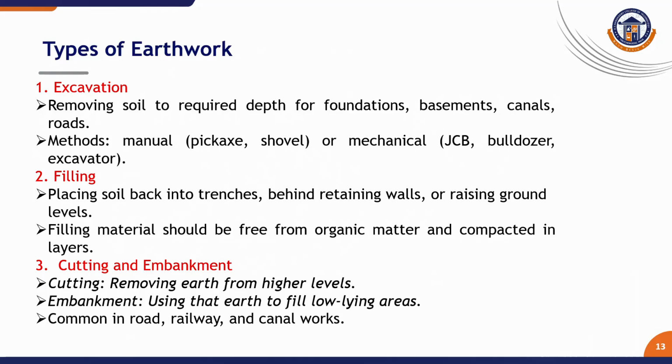Types of earthwork: excavation, filling, cutting, and embankment. Excavation means removing soil to the required depth for foundations, basements, canals, roads. Method: manual method or mechanical method. Nowadays mechanical methods use JCB, bulldozer, and excavator.